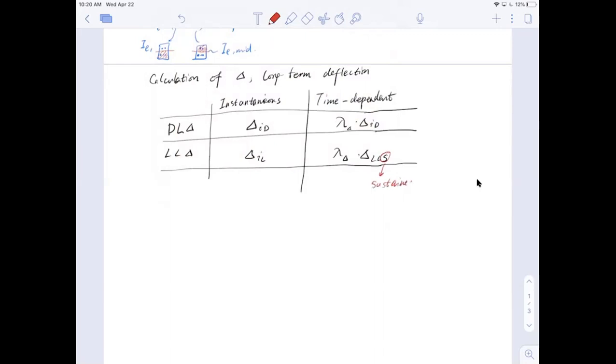We talked about this, right? There are several different types of live load. There are machinery that's going to occupy the floor for a long time, so that is a sustained live load. But there are live loads, for example humans, who walk on it, and those are not sustained. Sometimes they come off, sometimes they stay.